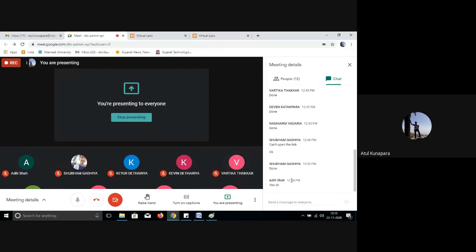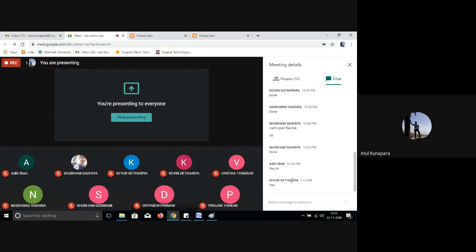Yes, sir. So the only thing you need to learn in D flip-flop is we are avoiding the simultaneous 1-1 condition coming on the input side by connecting both the inputs to a single input, that is the D input, by putting a NOT gate in between there. So either they both can be 1-0 or 0-1, but they can never be either 0-0 or 1-1, right? So that is the condition we are having in this case. So that is the D flip-flop.